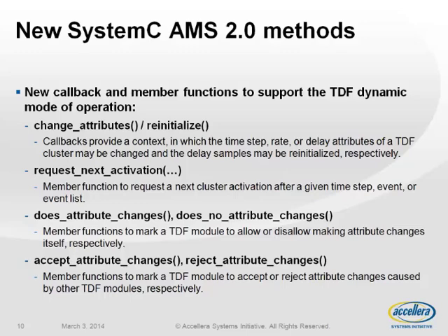You have the does attribute changes and does no attribute changes, which marks the module whether it will actively change anything in the TDF cluster, and the accept and reject attribute changes for whether it is able to deal with attribute changes or not. And then you have a new member function called request next activation, which enables you to become sensitive to events and to ask also for a reactivation after a certain timeout.